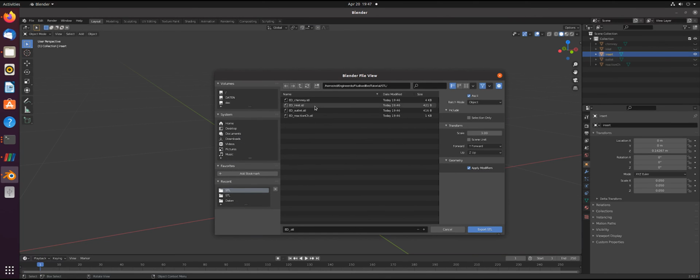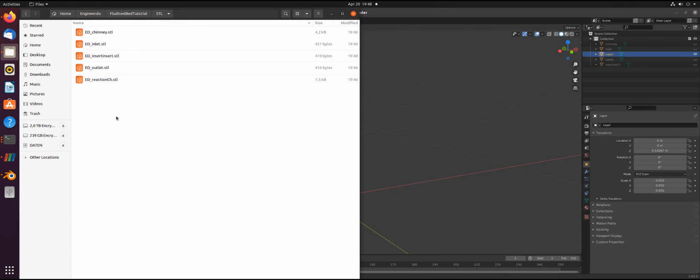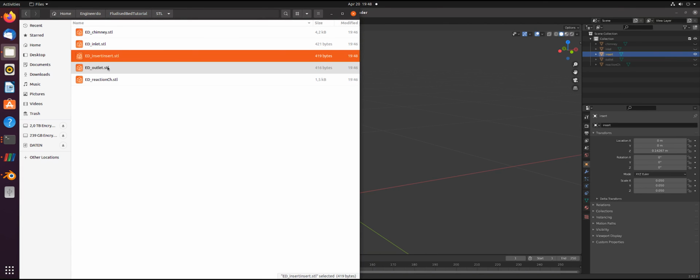To export this part, I will follow the same path after renaming the structure: File, Export, STL. But now I use the checkbox Selection Only to not export everything again, but only the insert plane. Therefore, I have to use a reasonable name, of course. I should have unchecked the object mode before. Now I have to correct the doubled names here.